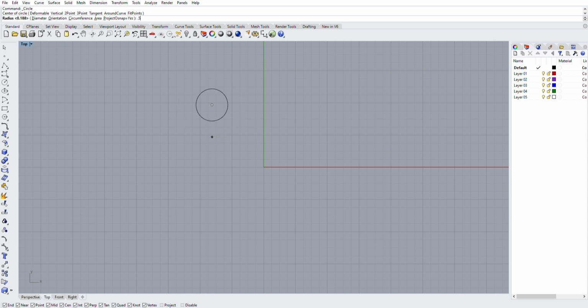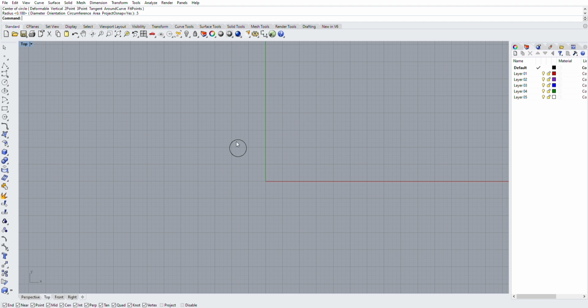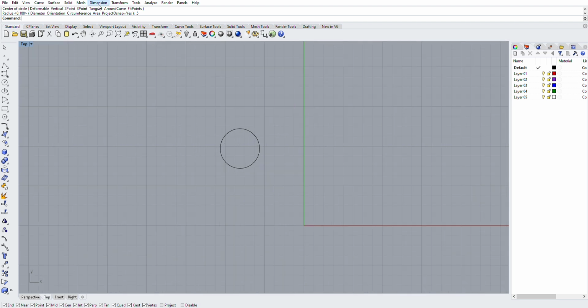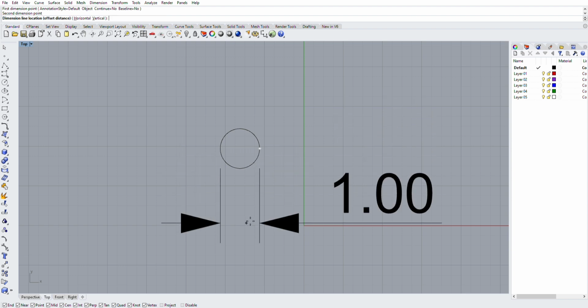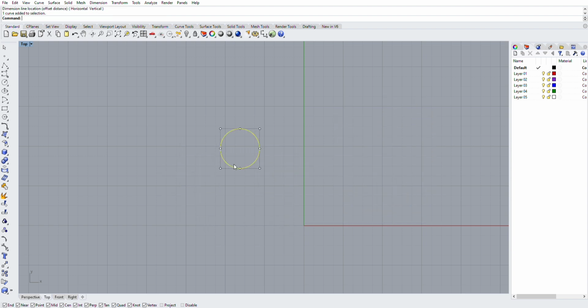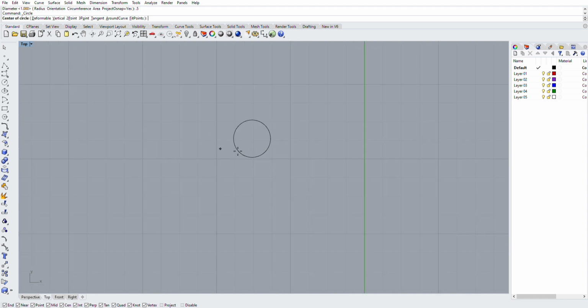This could be a tab for anything. Say it's a shock tab. We're going to start with our center hole, work our way out. It's a good idea to double check that you've got it on diameter and not radius. I wanted a 1/2 inch diameter. I had the circle tool set to radius. Double checked my dimension, it was twice as big. So start the point again, set it to diameter, 1/2 inch.